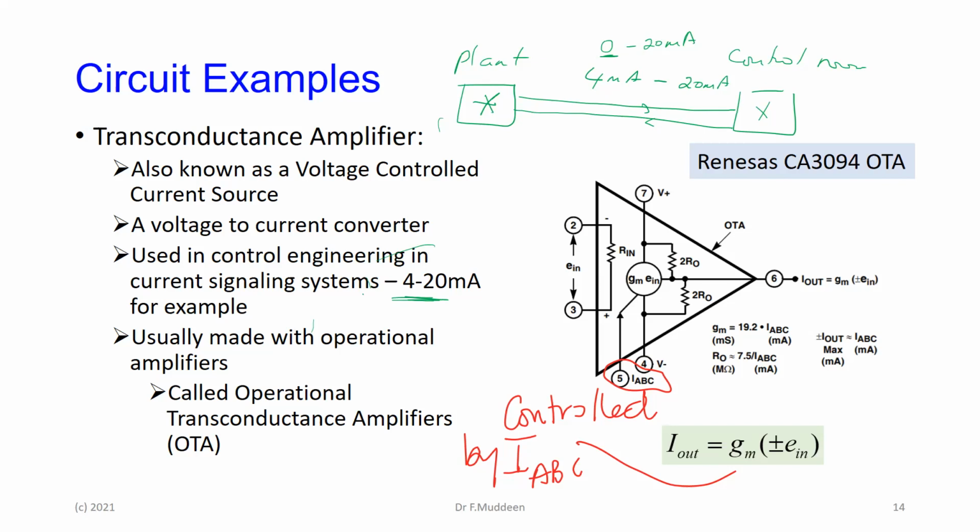All right. One reason is that if you're using 0, let's say just for argument, we are using digital signaling. So 4 milliamps is logic 0, 20 milliamps is logic 1. If I were to use 0 milliamps as logic 0 and 20 milliamps as logic 1, then there's nothing to let me distinguish a logic 0 from a broken wire.